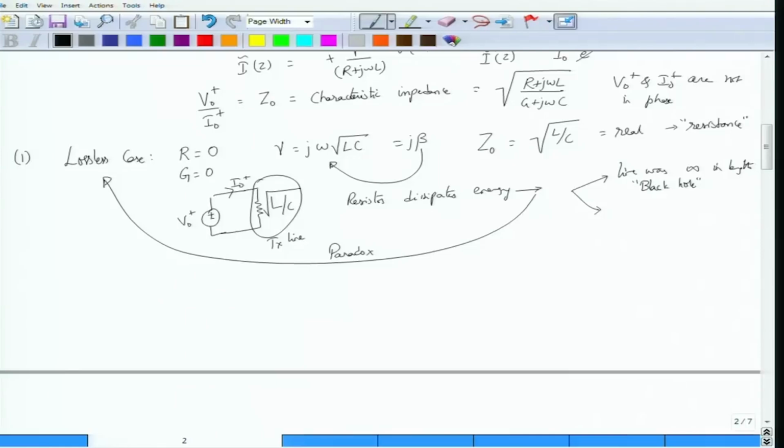So, in terms of the source, this is clearly a lossy transmission line, because the source has put out energy, but that energy is not coming back to us. Well, technically the energy would be coming back to us, because it goes all the way to infinity. Only, you have to wait for an infinite time, which practically means that amount of energy is simply lost on the transmission line. And that is what is captured by having a real resistance as an equivalent resistance for the transmission line.